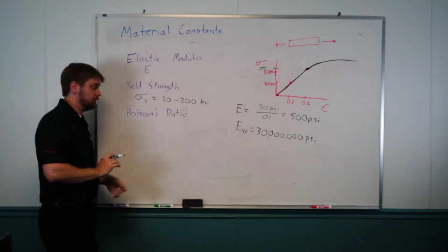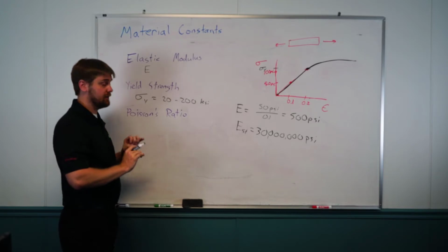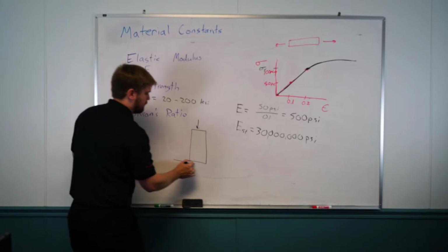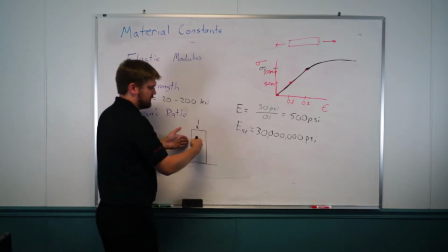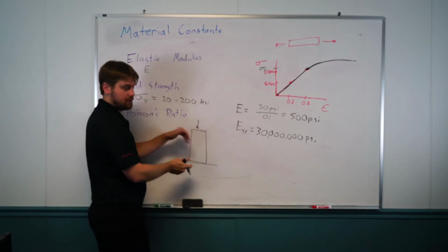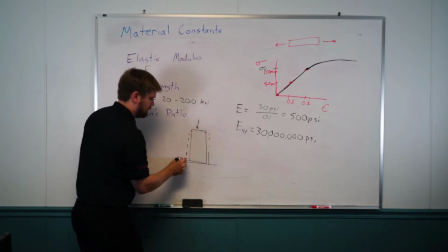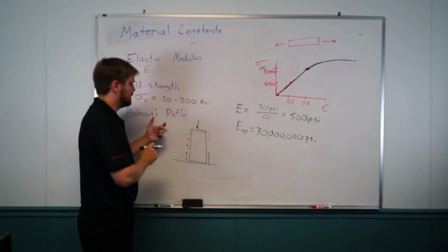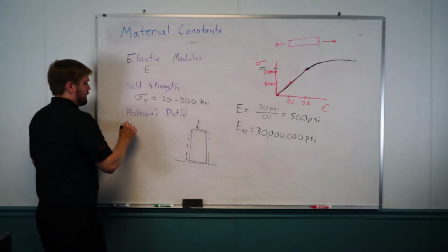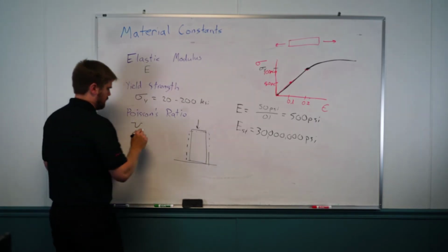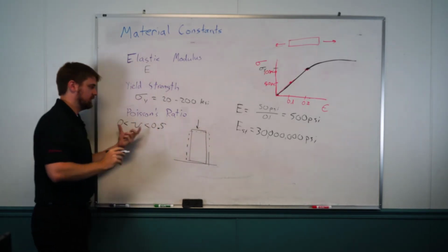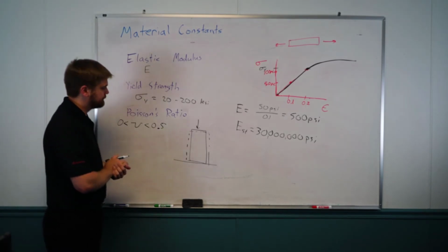Finally, Poisson's ratio, another important property for the purpose of our analyses, describes this effect. If I put a compressive load on something, it tends to strain in the other directions. It'll expand outward. So not only does it shrink a bit, but it also stretches a bit. And the degree to which it stretches is described by this Poisson's ratio. The ratio, described by the letter nu, varies between 0 and 0.5. If you look in the database, you'll see numbers between those two values.